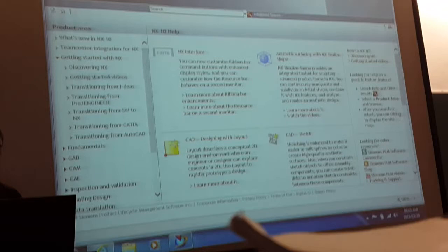And in the FEM model, what you are going to prescribe is the mesh and the material properties associated with that mesh. And then in the final step, we create a simulation model, finite element simulation model. Right, and in that step, we add our boundary conditions, so the constraints and loading. Right. Once that's done, we can perform the simulation. Right. So at most, it's 4 steps.